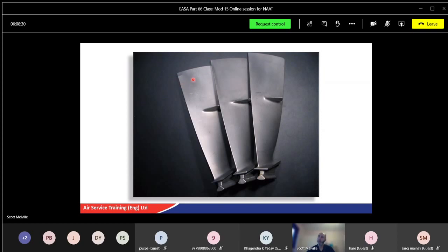So again, I can just see a tiny little dip on the top of the blade there, and very closely, you might never see this on your computers or what have you got at the moment. There's a tiny little nick just on the leading edge of that blade there. So again, some of the damage is not exactly obvious straight away. Take your time, and if you can feel it, run your hand up the leading edge very carefully. Don't do it too fast, because if there are any jagged bits sticking out, they'll cut you. So just nice and gently, using your hand as well as your eyes is a good way to find some damage. Okay, but take your time.